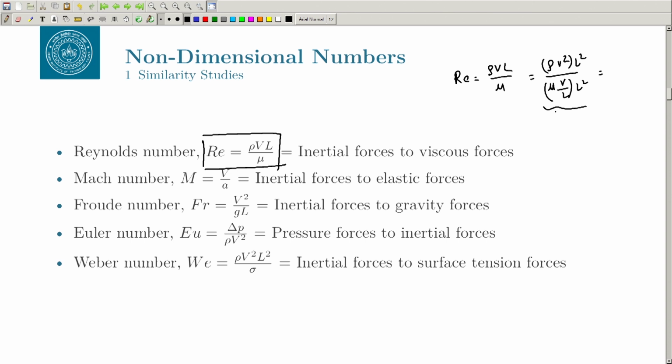If you know the boundary layer, and you want to find out what is the drag experienced here, the skin friction drag or the viscous drag, you can find out the shear stress, which is tau w, which is basically mu del u by del y at y equal to 0. So, this is your viscous force: mu multiplied by some velocity gradient. If you write in terms of dimensional numbers, this is like mu V by L. So, it represents your viscous stress.